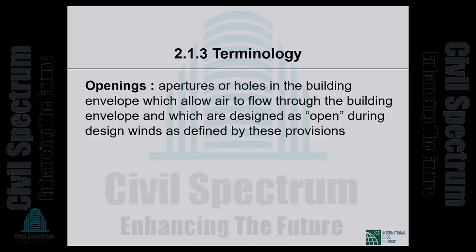If you have a roll down door, you still have to design considering it as an opening unless you have a crew in place, instructions in place, making sure that the roll down door will in fact be closed at the approach of a storm. If you don't have those things in place, then you have to take that roll down door as an opening. So that's kind of important.